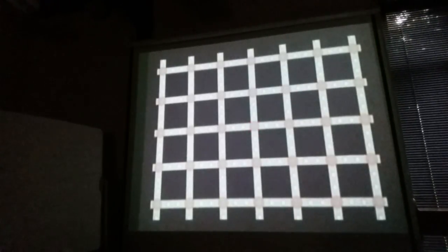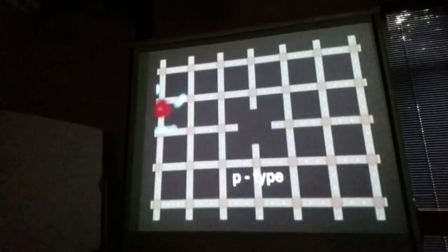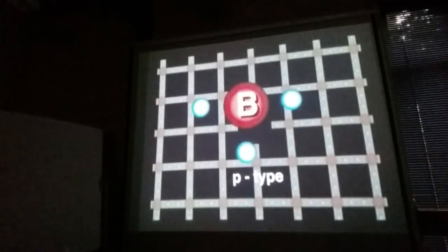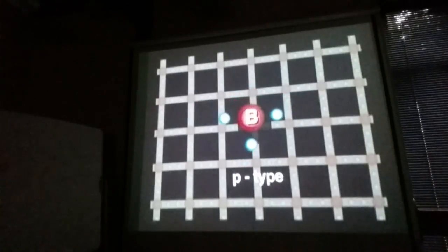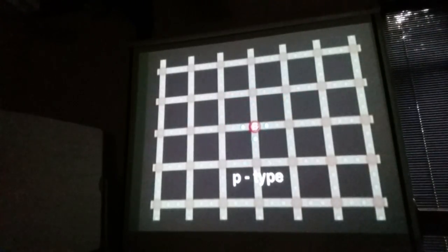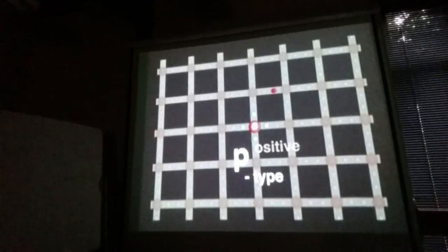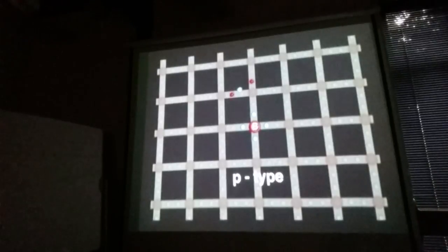One can make p-type silicon by adding impurities, such as boron, with only 3 valence electrons. It forms only 3 complete bonds with the neighboring silicon atoms, leaving one incomplete. This incomplete bond has the ability to capture an electron, usually a nearby electron from the valence band. This neighboring electron leaves behind a positive hole that can diffuse through the crystal at ordinary temperatures.